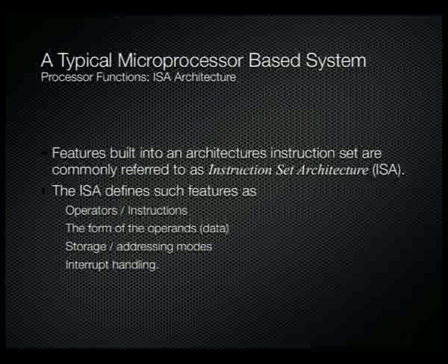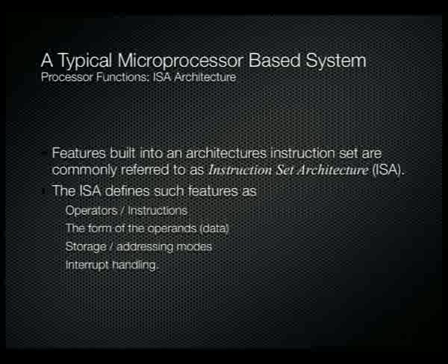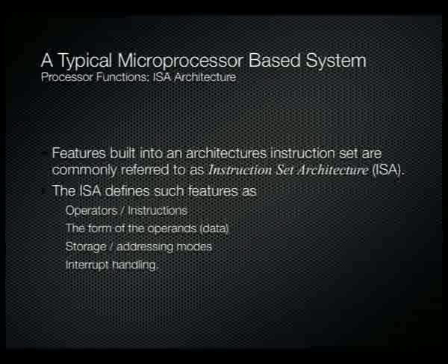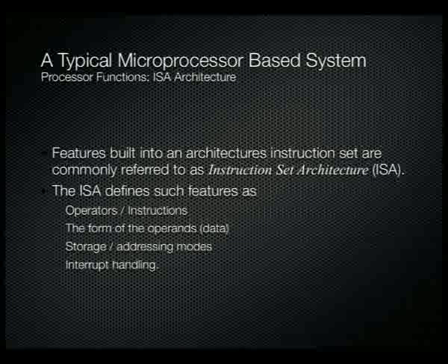The instruction set architecture effectively defines such features as the operators and the instructions, the form of the operands, or the data for those instructions, the storage and addressing modes that we have inside our microprocessor, and of course the way that we handle our interrupts. So when asynchronous events take place and we have to stop what we're doing and service those asynchronous events, how do we do that? That's all defined by the instruction set architecture.